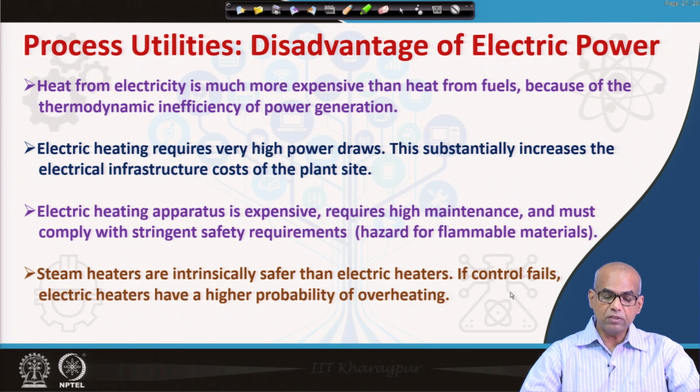Steam heaters are intrinsically safer than electric heaters. The highest temperature that can be obtained with steam is fixed by its pressure. So, when control fails, electric heaters have a much higher probability of overheating. So, steam heaters are intrinsically safer when you compare them with electric heaters.